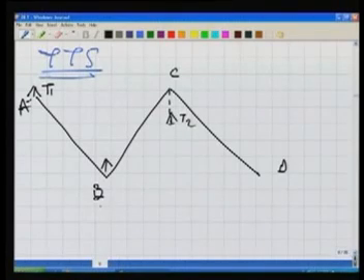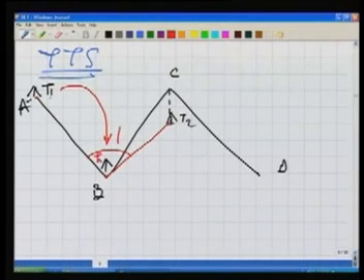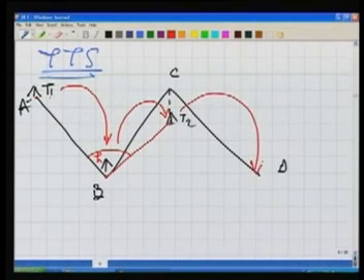From B, the angle between these points is measured. So from B I bisect target number 1 and then target number 2. Because of this miscentering, the angle measured is wrong. Next, this target will move to this tripod, and the theodolite moves to this tripod, and this target T2 moves to this point.